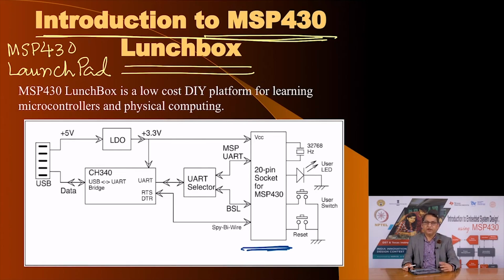The third method is using what is called in-application programming, what Texas Instruments calls the bootstrap loader, and the advantage of that is you do not need any special mechanism to transfer the program from your development host, which is the desktop or laptop computer, into the memory of the microcontroller.